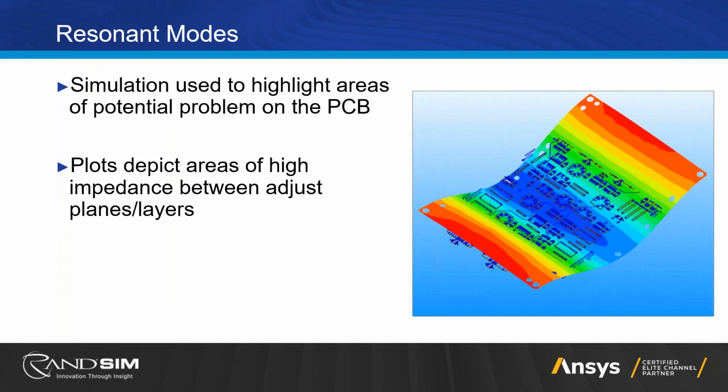The next thing I want to jump to is resonant modes. So when we're talking about, in this case, power integrity, resonant modes gives you insight into coupling between planes, on layers, and it can give you a glimpse into where you may have higher than expected impedance on these different layers.